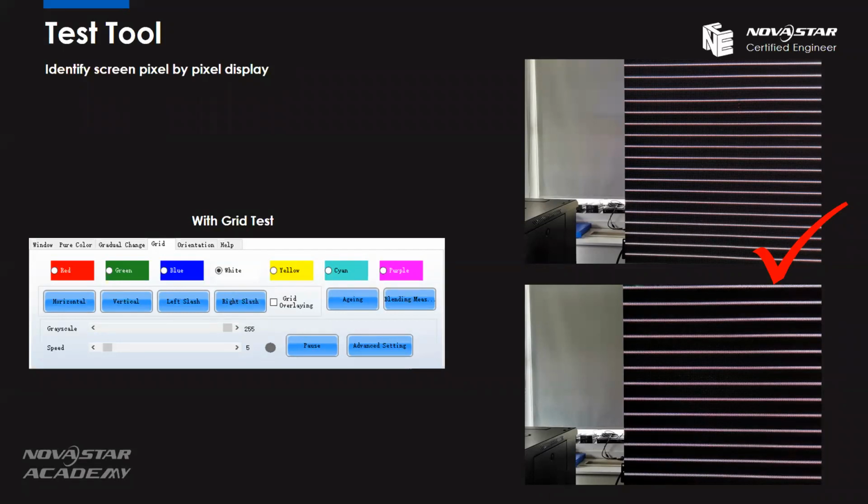And even when the engineers from the manufacturer or from Novastar are doing the smart setting to create a new RCFG file, we always need to make the screen pixel by pixel. And besides, when we're doing the on-set calibration, pixel by pixel is also very important, because the calibration collects the information of every single LED dot, color and brightness. So pixel by pixel is very important.